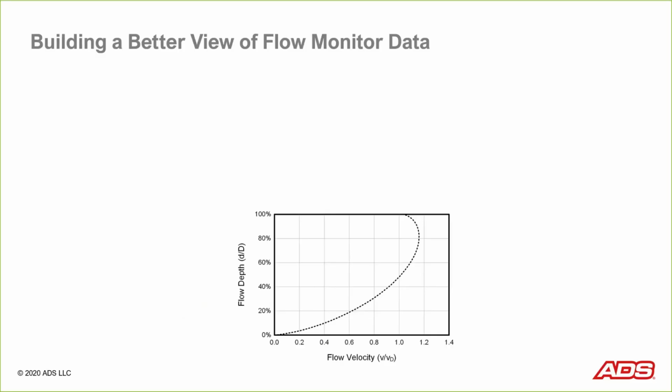Now, I'm going to make a few changes to this graph to provide something that I call physical perspective and context. It's actually going to help us understand the data a little bit better. So, watch with me here. I'm going to pull this left axis out, and then I'm going to drop in a cross-section of the sewer pipe. Now, this is not something that you see as much on graphs in a modern hydraulic textbook. But if you go back to some of the textbooks, say in the early 20th century, you actually find this feature on a lot of them they use for the Manning equation.